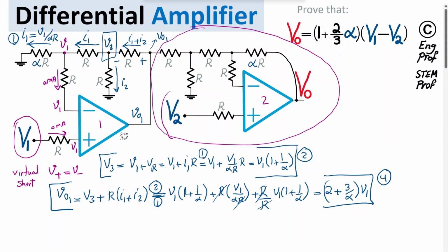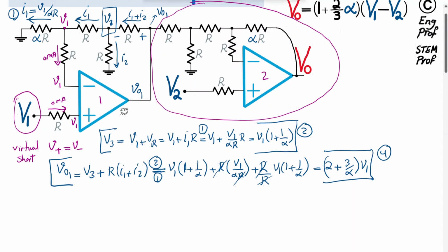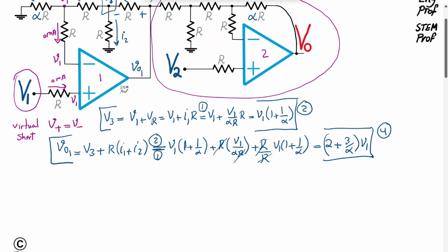As you can see, we effectively have two voltages applied to the second stage. One, we have voltage V2 at the non-inverting or positive input terminal. And then we have voltage VO1, which is coming from the first stage and applied to this network of ladder resistors, and then we have the connection to the negative or inverting terminal. So I can use superposition now. The reason for that is, of course, I could use the circuit laws again, but superposition has the benefit of making things a little bit simpler.